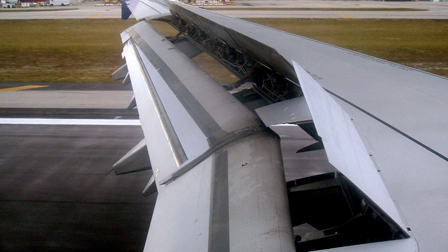They form part of a speed brake system which can be used to slow the aircraft down in flight and on the ground. When operated, they reduce the lift on the wing. Thus, in order to maintain altitude, the aircraft has to be pitched up, increasing drag and reducing airspeed.